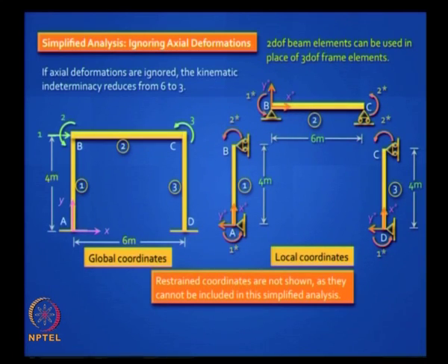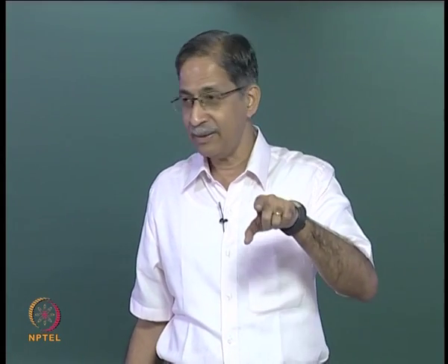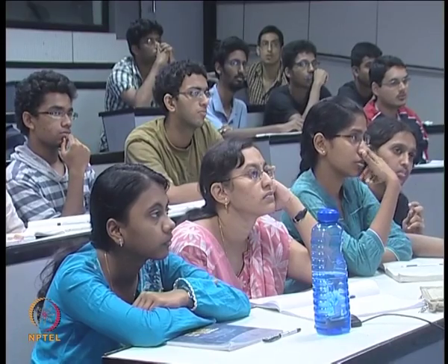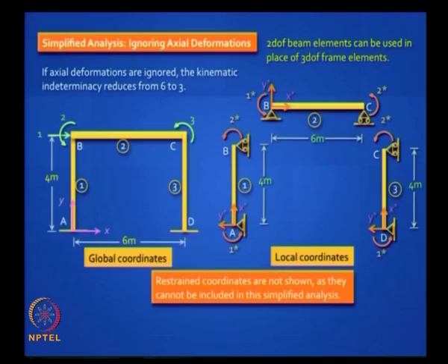You understand? Now how did you do it in slope deflection method? Let us say that portal frame D goes down by 10 mm. Earlier you could handle it because in the dr vector you could fit it in. Now what do? In the fixed end force you have to handle it, because if D goes down by 10 mm, C also will go down exactly by 10 mm if CD is not going to change in length. BC will undergo chord rotation, and that you can get the fixed end moments from. So that is a clever way of doing it, and that is what we will do.